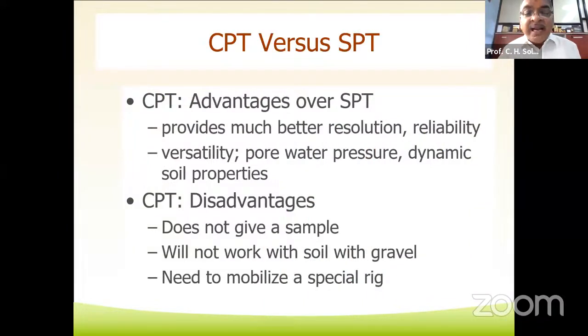Now, what are the advantages of CPT versus SPT? It has been mentioned here. The advantages of CPT versus SPT are much better resolution and reliability, versatility, and pore water pressure and dynamic soil properties can be determined in the case of the CPT test.